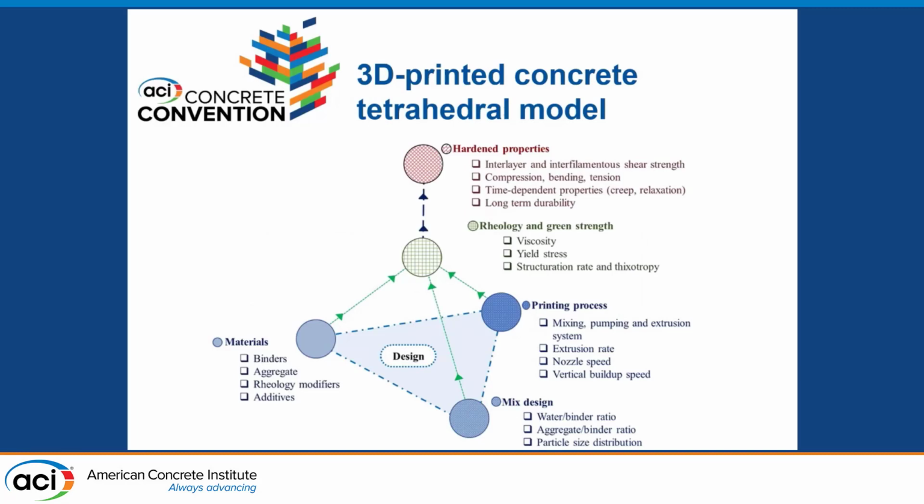When we look at material selection, I think we have to think of everything that is involved. We have starting materials, which are typically the same as for making concrete, but with more requirements in terms of particle size and chemical compatibility. Then we do a mix design process, so we will suggest some ratios for water-binder and aggregate-binder. You will see some in this presentation.